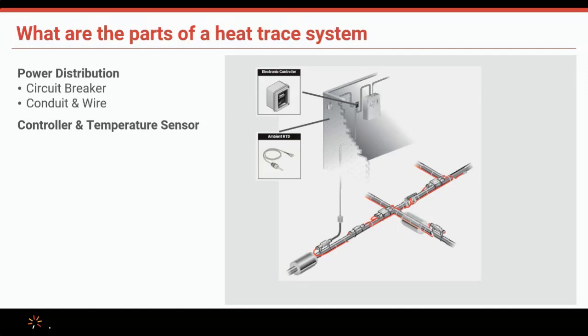However, there are things to consider for your client and the specifications. Without a controller, you have no way of completely turning off that heat trace. So even though it does self-regulate, if someone forgets to turn off that breaker in the springtime, it will continue to produce a minimal amount of heat throughout the summer months. And so it's really just an energy efficiency thing, and also life expectancy of the cables. So we do really encourage some type of control. And again, we have several types, so we can have that discussion on what the best is for your client.